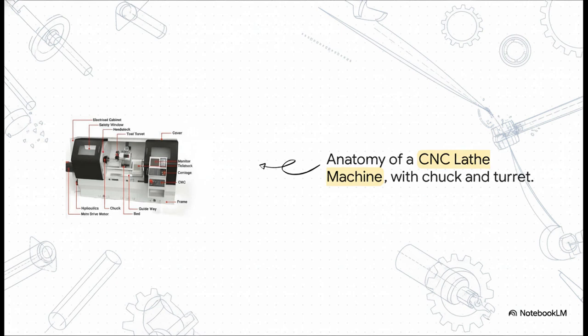Now, compare that to a completely different beast, the CNC lathe. In a lathe, you have a chuck. It operates by holding the raw material in that chuck and spinning the material itself at incredible speeds. Meanwhile, the cutting tools, which sit on a tool turret, remain stationary but slide along the guideway to peel away material from the spinning metal. It's so cool to see in action.